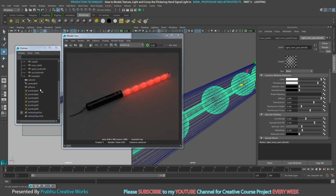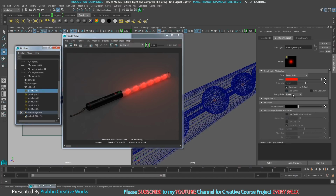Then I will select all point lights and set the decay rate to quadratic, and give much more intensity, so I will give 7, I think. So you want to give quadratic and give 7. You want to manipulate this for our final touch. So I will change all my point lights to quadratic decay rate and change my intensity. So I will compare.